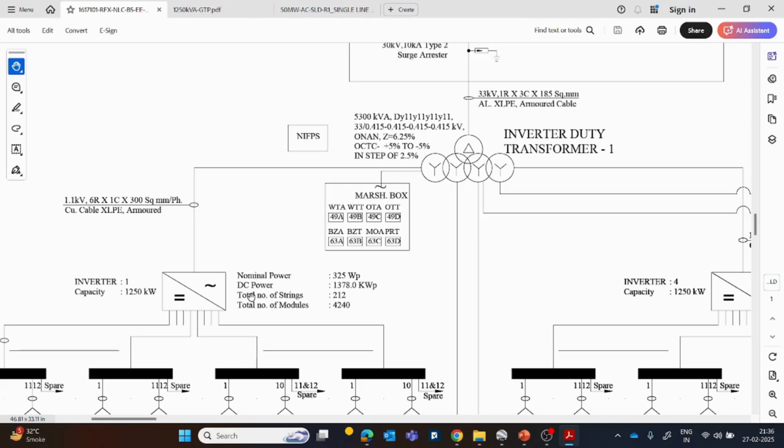The transformer capacity may not reduce that drastically, but the PV maximum power or the battery storage export maximum power is going to decrease at a slightly higher rate than product degradation. You can even ask your supplier for a transformer degradation chart before ordering. Generally, they will commit to about the same life.